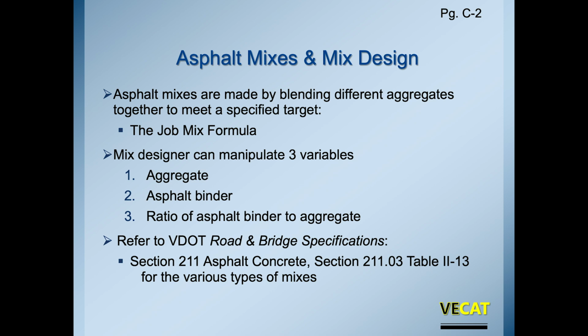Now I'm going to ask you to refer to your Road and Bridge Specifications for VDOT, which is what this presentation is based around, and specifically section 211 for asphalt concrete, which has table 211-3 and section 211.03 for the various mixes that are used.